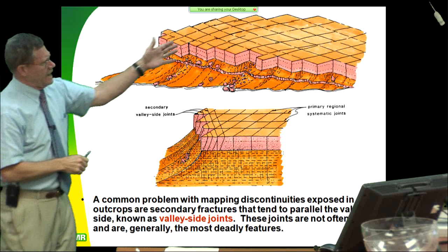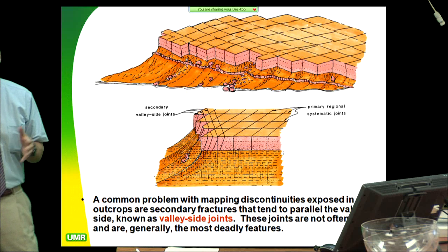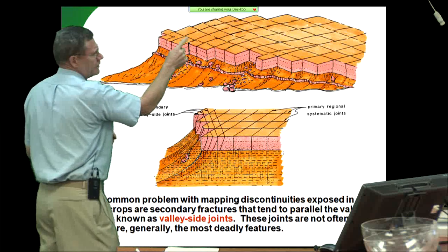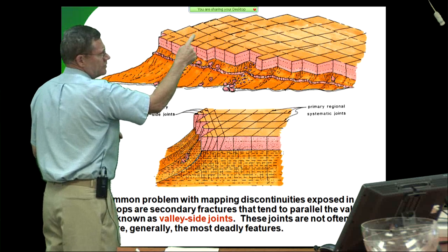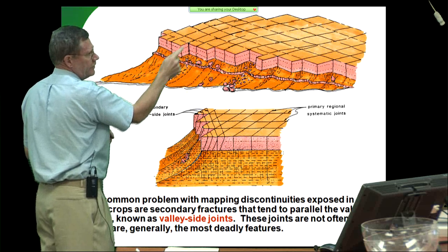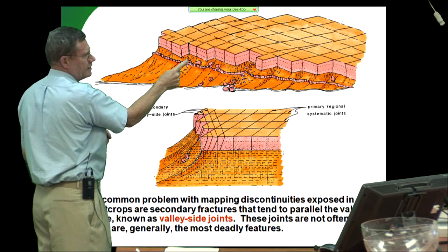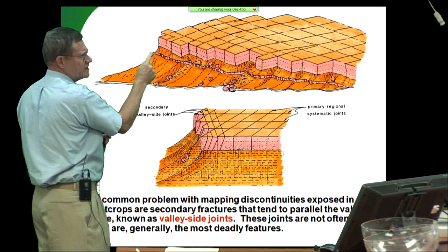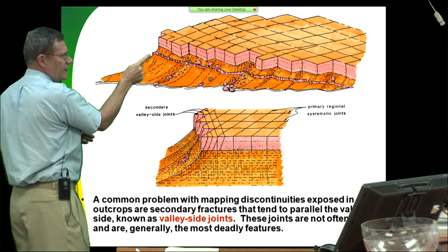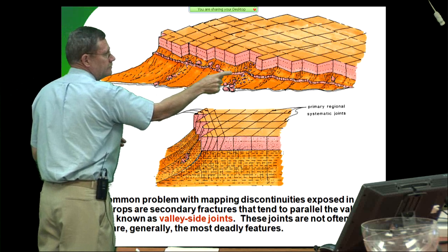And so the water travels through the joints. Water doesn't travel much through the rock itself. If you're going to go out and monitor a place for groundwater, or you want to monitor it for anything that has to do with fluids, you've got to drill angled holes that pierce these semi-vertical joints. Now if you look down here, you have another little bed of sandstone, but it's much thinner, so it's less stiff, so it's the same joints, same orientations, but much more intense, much closer together. And that's pretty typical anywhere you go.